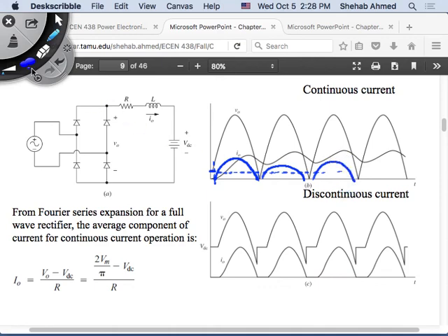Right? Now we have an inductive circuit case. In the inductive circuit case, what happens? Current starts rising in the same place, but the shape of the current is a bit distorted. Right? It will be delayed. The peak will be delayed with respect to the resistive case. And then it tries to start falling down. It will fall down after the resistive case. It can fall down here in the middle, if you've chosen the inductor value as such, but it won't happen. That would have happened only in the half-wave rectifier.